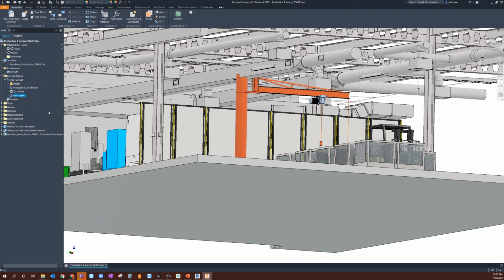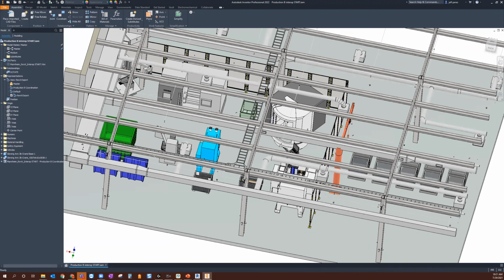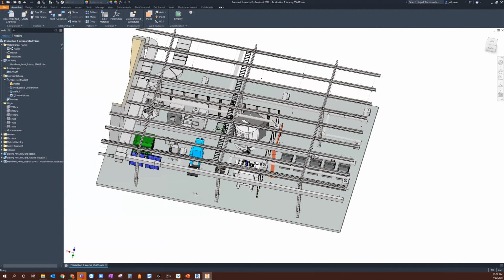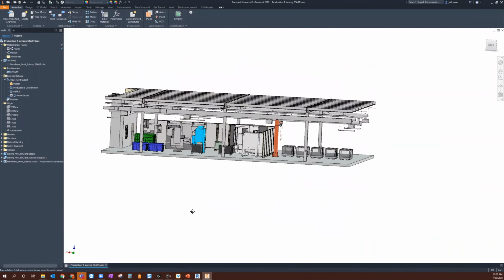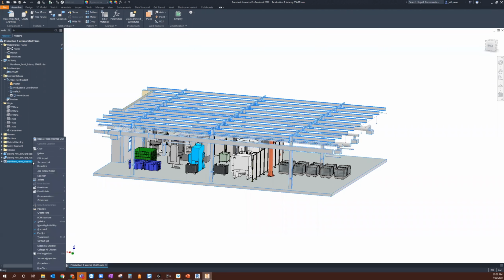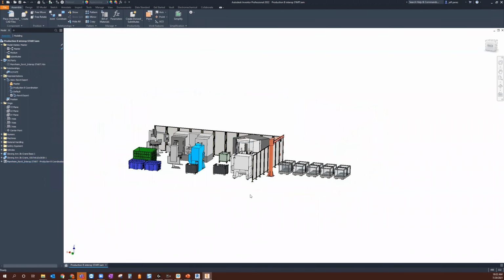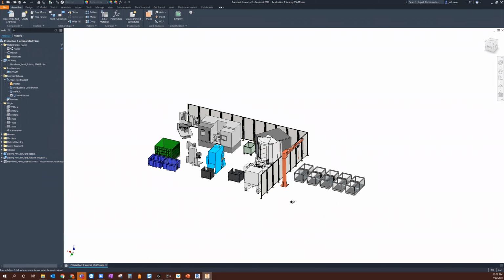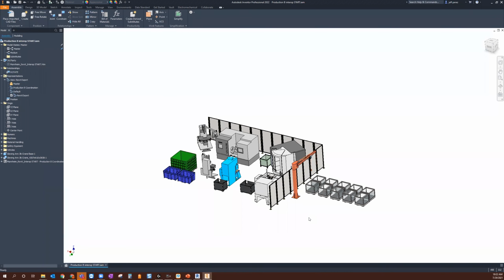that is a Revit export. And inside of this Revit export, I've already gone through and turned off humans. I've turned off any other pieces of machinery that I probably don't need to incorporate inside of this exported coordinated model that we're going to be providing to this subdiscipline. But what I'm going to do a little bit more is turn off this building, okay? Because I just want to provide... I'm going to right click here and turn off the visibility. I just want to provide my industrial equipment, or my piece of machinery, for coordination purposes. You can see all we have left are the assemblies and the part models that I have inside of Inventor.